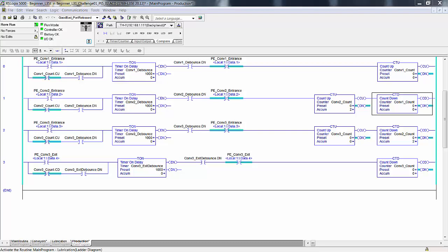Well, it sounds like we're repeating, and we are, because the logical conditions can change between step 1 and step 6. Let's say the conveyor is only long enough to buffer 2 cartons, meaning to have 2 sitting on the conveyor and then consider the conveyor full. Now just in looking at the diagram, the illustration, you could probably squeeze another carton on there if you wanted to keep the cartons closer together.